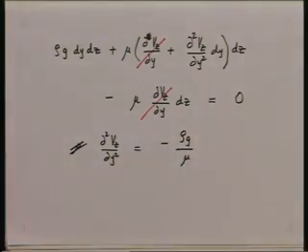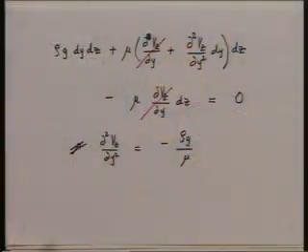So, d2 vz dy squared is equal to minus rho g by mu on simplification. So, the application of Newton's second law to this control volume dy dz, with the simplification that momentum effects in and out of the control volume are negligible, gives me this very simple differential equation.